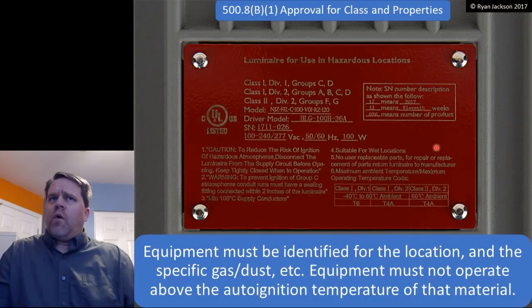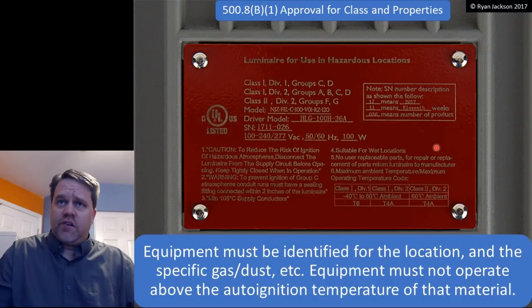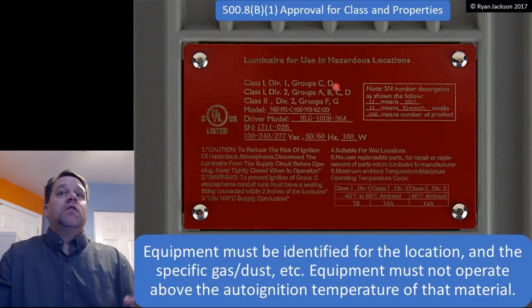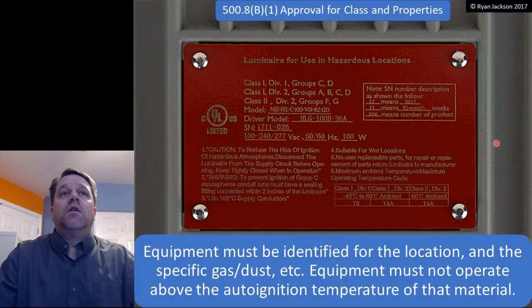We're going to talk about what we call T codes here in just a second, but that has to do with the auto-ignition temperature of the material. What is making my location a hazardous one? Is it acetylene? Is it butadiene? Is it gasoline? Is it propyl nitrate? I need to know these things because I need to know what? The auto-ignition temperature of the material. Luminaires have a lot of surface heat. I better make sure that it doesn't have so much heat that it blows up the building, right? So I need to know what the auto-ignition temperature of the material is.